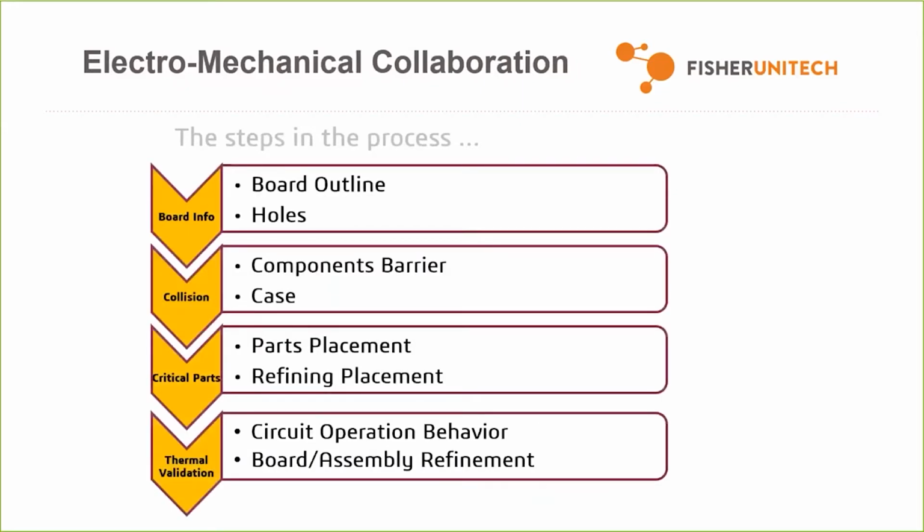So what's the point? Why have a PCB tool? Why go about collaborating between PCB and mechanical? Well, essentially, the mechanical designer is usually responsible for things like the board outline, maybe mounting hole locations, collision of components, parts placement, so critical parts placement. You can think of your connectors, your push buttons, your screens, and ultimately even things like thermal validation.